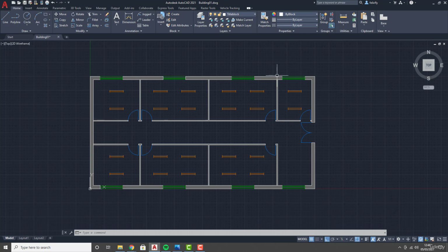Oh, okay, I'm going to draw this. It's actually going to be 10 centimeters wide. Therefore, this room needs to be. And if you see what I mean, you'd have a calculation to do every time you created a new object, how that would scale down. You don't need to do that in AutoCAD. You shouldn't do that in AutoCAD. It defeats the whole object of using AutoCAD. You may as well be using something like Paint or PowerPoint, okay? AutoCAD is a precision drafting tool, and you draw everything at actual size. So we draw this at 20 meters wide, the way it wants to be.